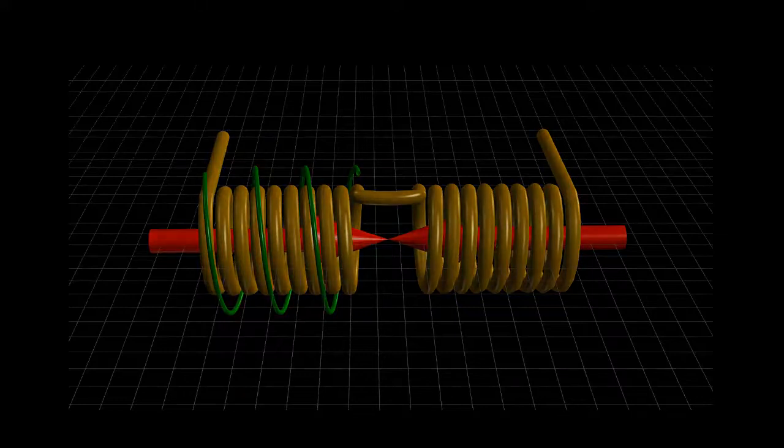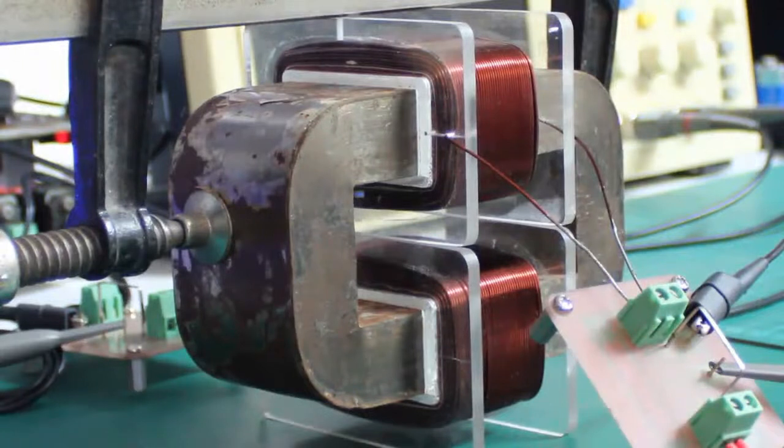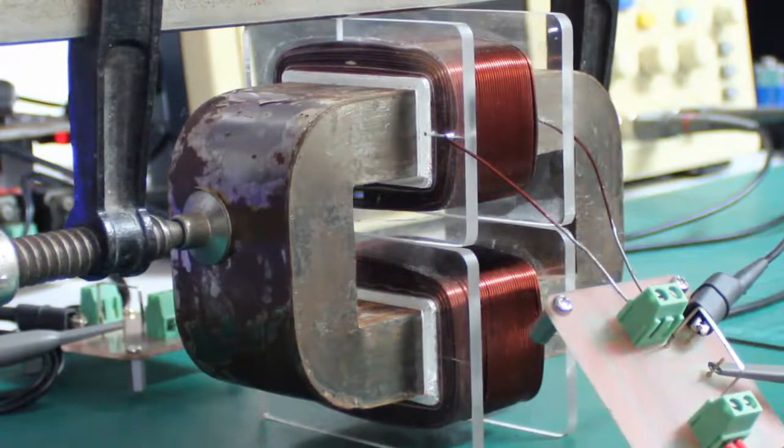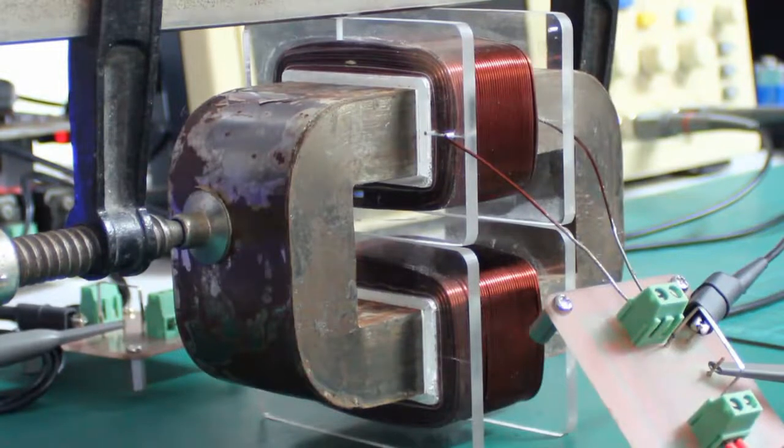What we've shown so far through this video is that the change in current can be introduced anywhere. We need a change in current to get the voltage up, but the propagation around the core to the second output coil is relative. It's a time factor that we can take into account, and it's negligible. The delay that travels around the core is very small. That also means there is a factor where we can predict to a certain degree the time it's going to take for one coil to see the change in the other coil. Now that we've measured it, we can predict it.